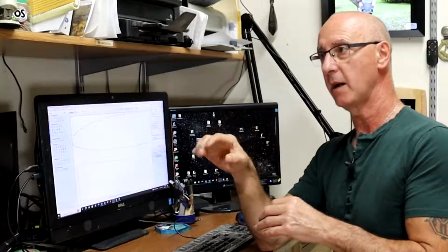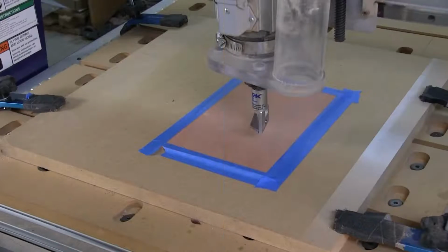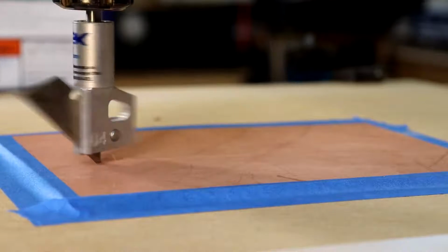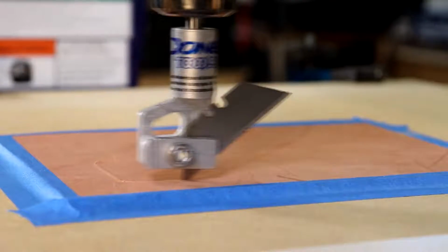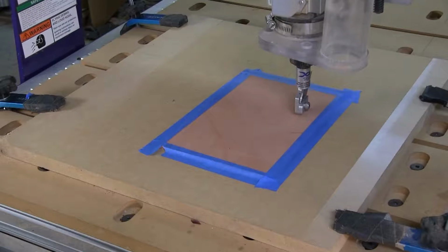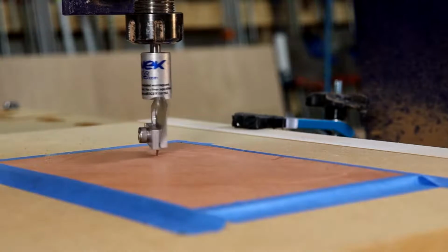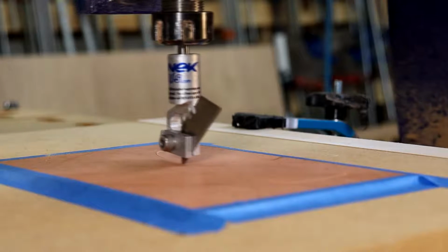So that takes care of the software side of this. Let's go look at the hardware side. Let's have a look at this tool path running on our CNC machine. The drag knife enters the workspace, and then watch on these corners a little uplift, turn, uplift, turn. Watch here in slow-mo where you can really see uplift, turn, re-entry, uplift, turn, re-entry. That's how the gadget makes those sharp corners.